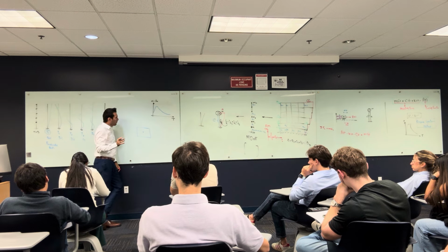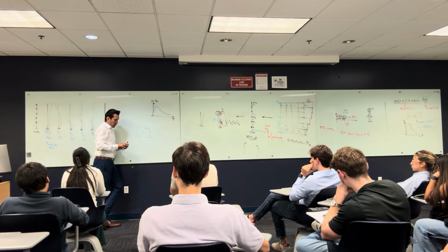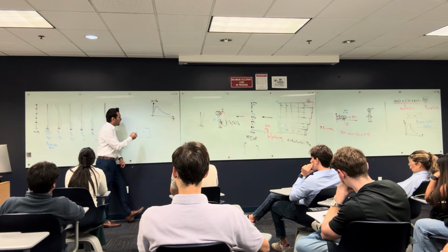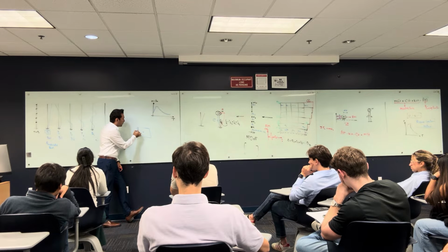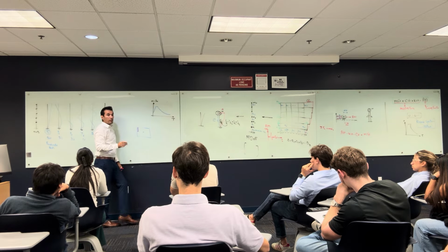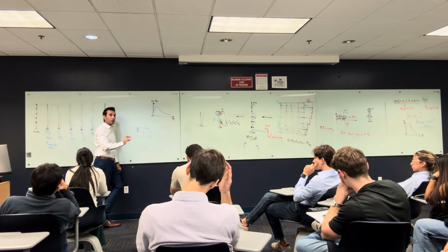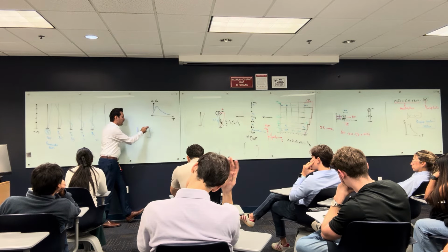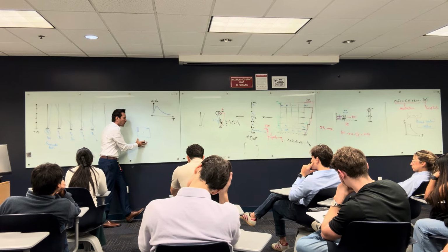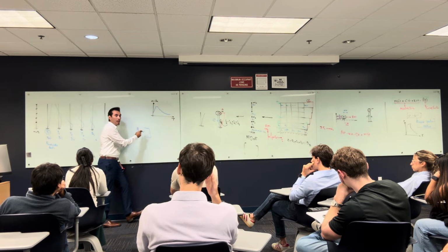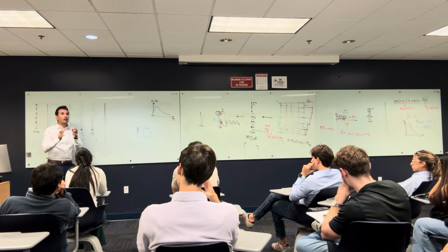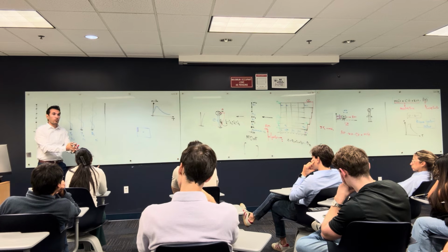I was like, oh, my structure is really, really weak, and I'm gonna put a shear wall here. All right? There's something called center of mass and center of rigidity. Center of mass, this is your slab, and this is the source of the mass. This is the center of your mass. The rigidity is the columns and the walls that make your structure rigid.